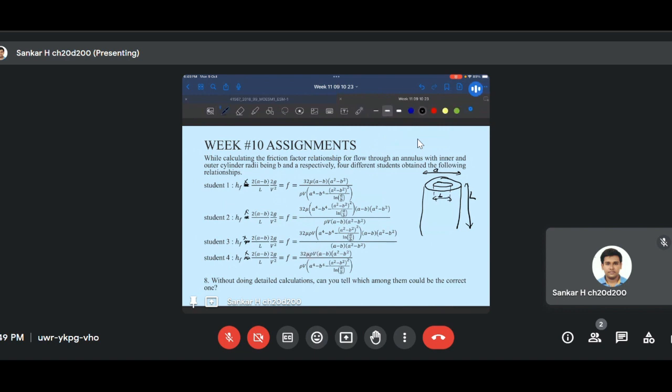this is again a mistake on my part where I copied it wrong. Yeah, so you can see that mu rho v comes on the numerator, so we can automatically neglect that. Then a dimensional analysis of this and this needs to be done. What you can see here is there is an effective length scale of L power 4 that's coming out from this, whereas here this is L and this is L square, which will effectively give an effective power of L cube.